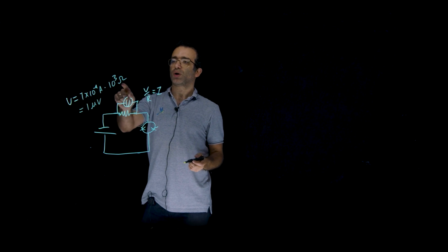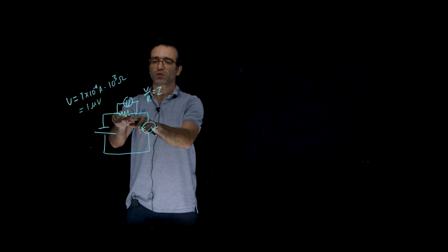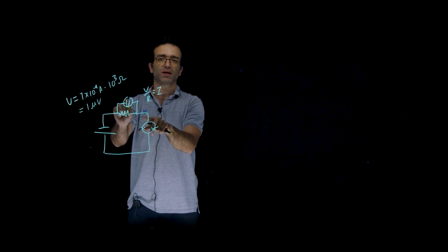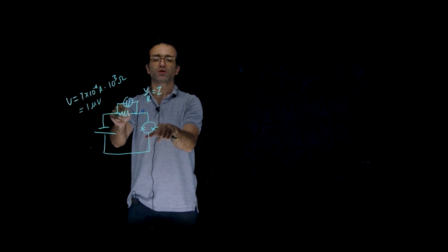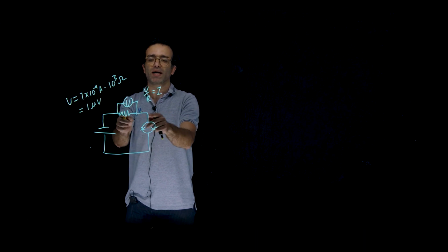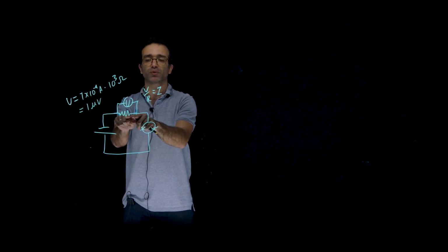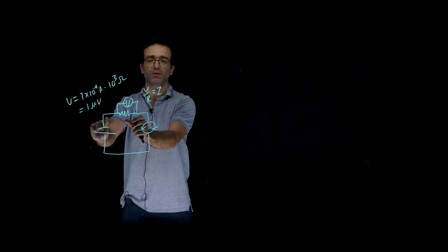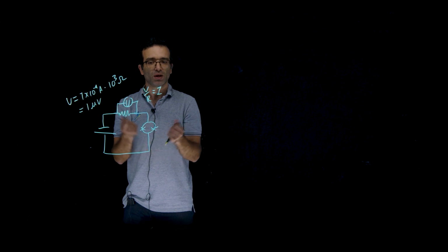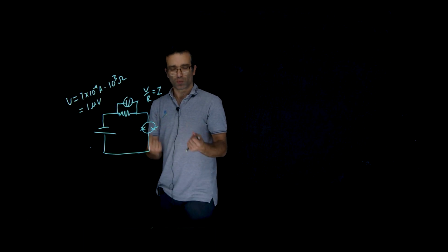So if I put here 1 kilo ohm, this 1 kilo ohm resistor will be much larger than even the normal state here. So essentially you can disregard this from the circuit. Whatever happens here doesn't matter, and the current is set by this resistor and the voltage that you apply here. So effectively what you're doing is a current bias. So that doesn't work.